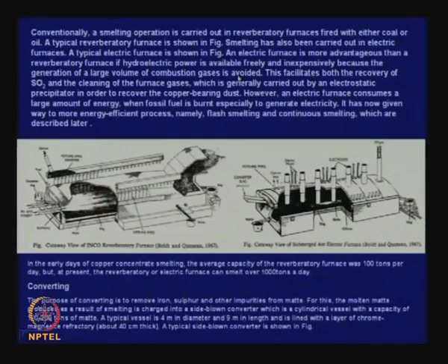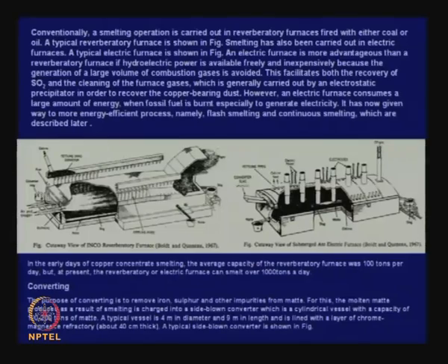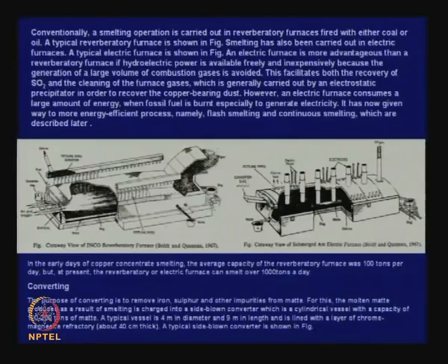When you are using coal or liquid fuel, a lot of SO2 is coming out from the system, but you would also generate CO2. The amount of combustion gases coming out will be much larger. In the arc furnace, you are only getting SO2, you are not getting the CO2 that will come from combustion of oil or coal. So, that will be an advantage of the electric arc furnace. However, the electric arc furnace can only be operated where electricity is available.